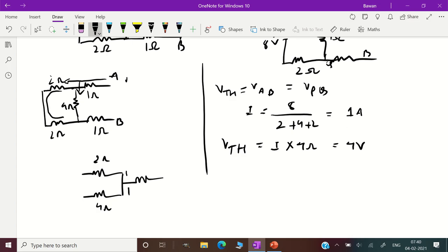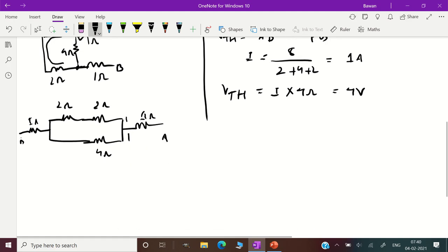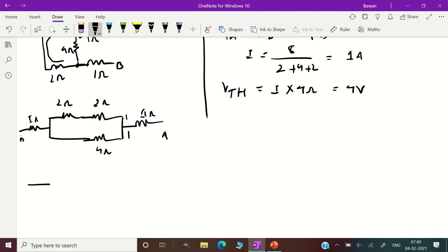It meets this 2 ohm resistance. So basically this is another 2 ohm resistance here, and again it meets the 4 ohm branch here. So let us connect it together, and finally from this point it goes to 1 ohm. So that is AB. This is my resistance, and if you calculate it, this is 1 ohm, also 1 ohm. So it'll be 2 parallel 2, 2 series 2, so 4 parallel 4. So it looks something like this, and something like this.